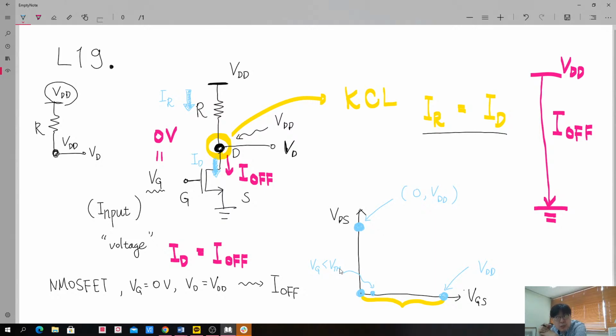Yes, now our transistor is still turned off, although you know that the current itself is significantly increased. However, since Ioff was so small, still we have so small current. So if we just consider it as negligible, then now we can say there will be almost no change in output value. So are you all with me?